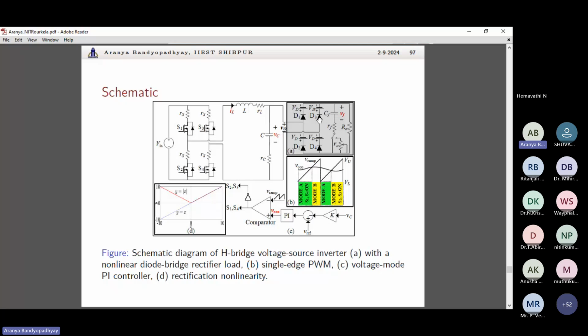And in the switching frequency based modeling for stability analysis, note that this diode would basically be left out. The switching phenomena would also be left out, but that doesn't mean that the non-linearity of it needs to be disregarded at all, because there is an additional capacitor at the output of it. We need to always remember that. And these would basically contribute a type of weak non-linearity at 50 Hz, not at the switching frequency.